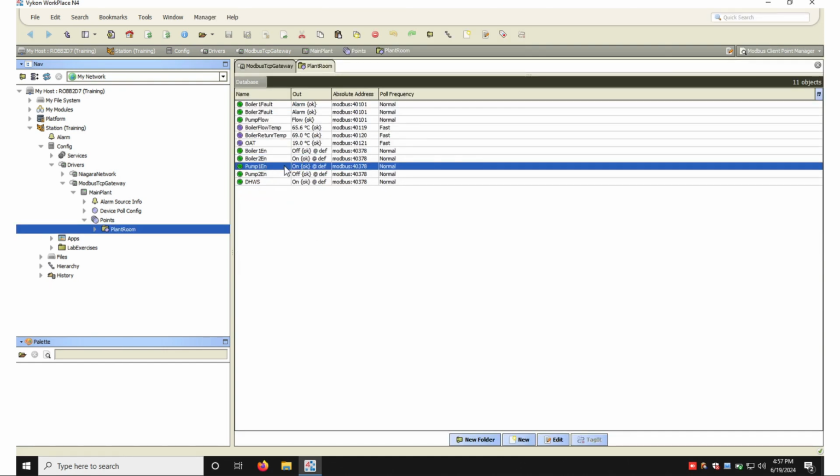So at 9 o'clock in the morning, the schedule will become active or true. At 5 o'clock at night, it'll go off. So 8:59, it's off. 9 o'clock, it goes from a 0 to a 1, writes to the Modbus point and turns it on. 5 minutes later in the real world, an engineer comes along and turns the panel off where this I/O module is. It power cycles, he opens a door, and then he turns the power back on.